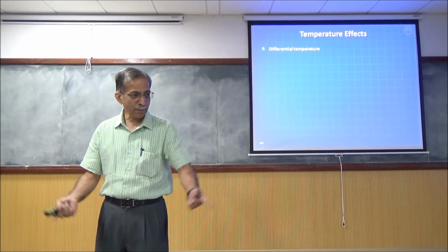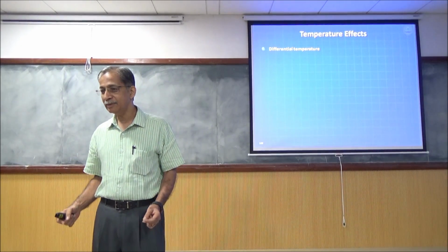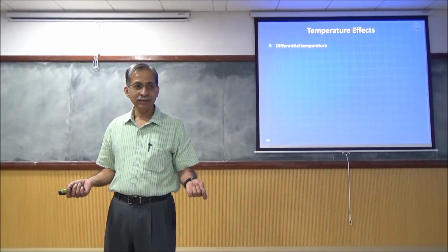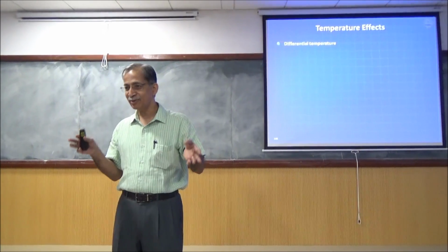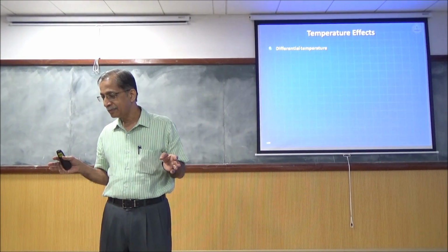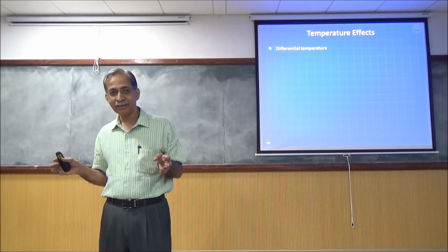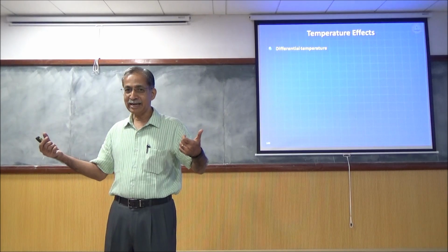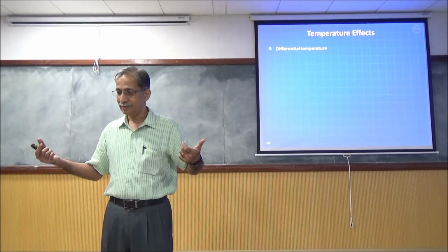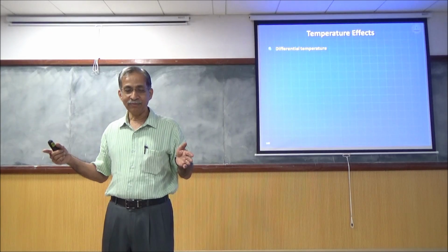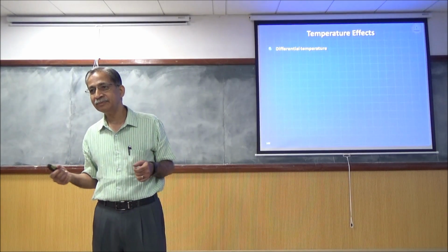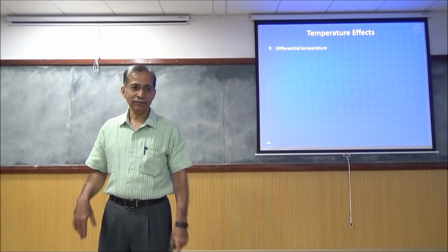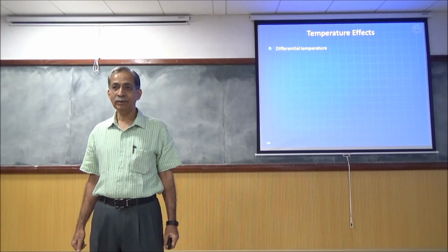Quickly, tutorial problem. You're going to get a tutorial next week or the week after that. The deformation is alpha T L, alpha being the coefficient of thermal expansion. Let's say alpha is given to you, then you can work out the change in length, L alpha T, or the strain is alpha T. From the strain, how do you get the force? Well, you know the axial stiffness is EA by L, you can work it out, right? It's a huge force. You'll end up pumping steel.